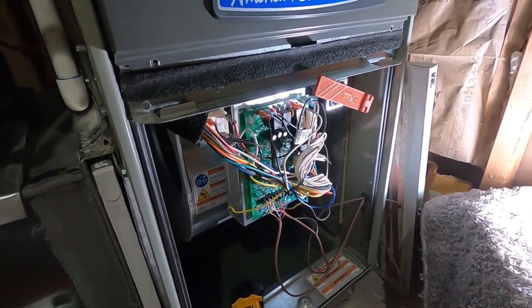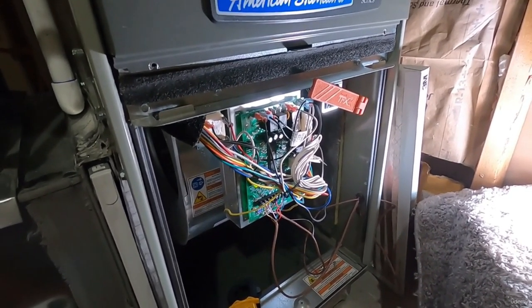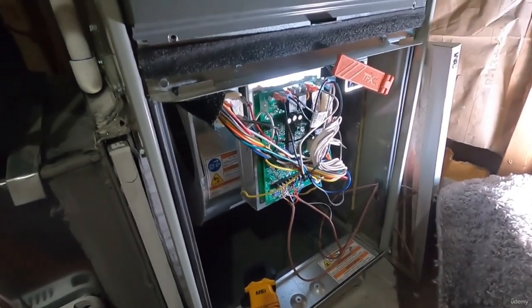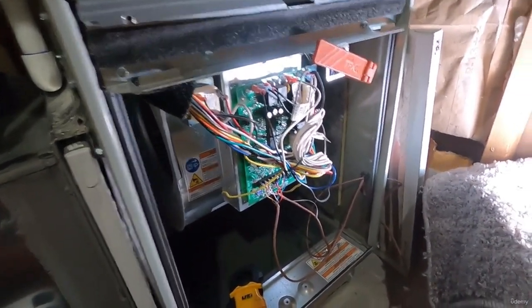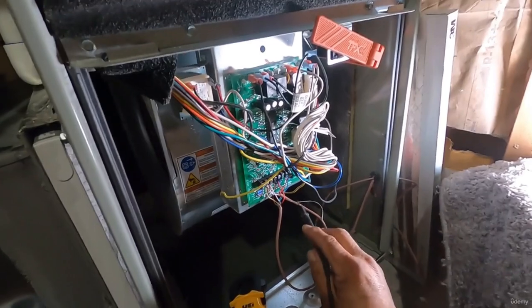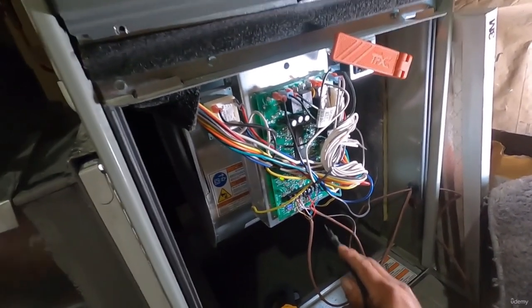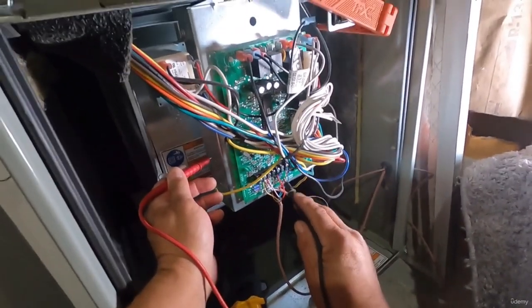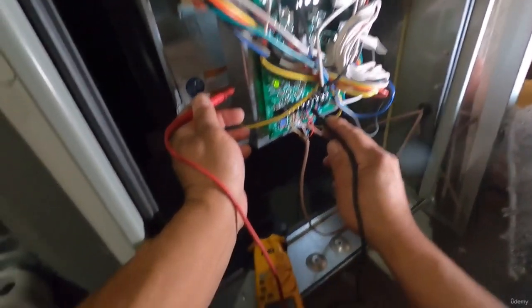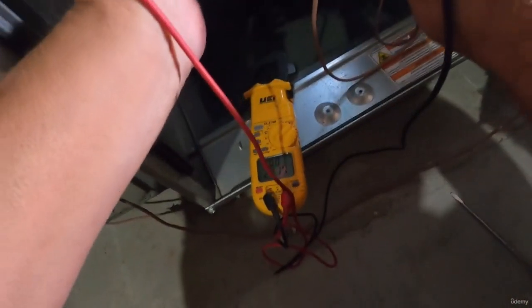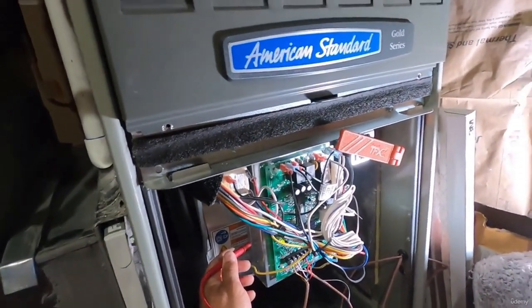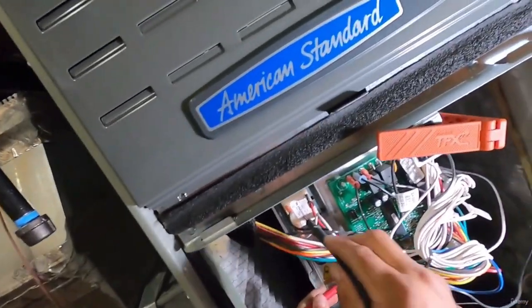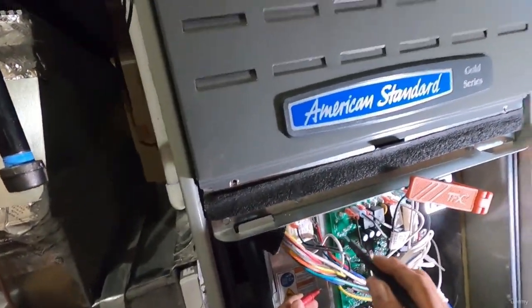Okay guys, now if you turned your thermostat to cool, you've lowered the temp for the air conditioner to come on, and if nothing happens, then you're going to have to come down here and test for voltages. So what you want to do is remember there's always power on the 24 volt R terminal. So if you go to ground and you put your lead on the R, you get the 28 volts, which I'm getting there. Hopefully you can see that. If you're not, then you're going to have to come back here to what's called the transformer to see if you're getting 24 volts out of that.